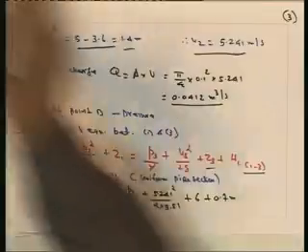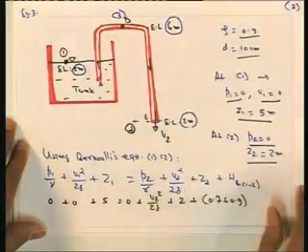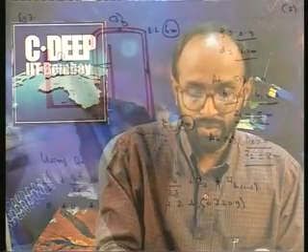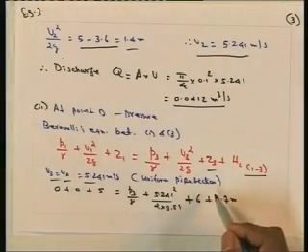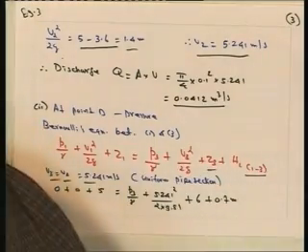Here you can see that this section is at elevation 6 meter from the datum. So, plus 6 plus the head loss between point 1 and 3, which is given as 0.7 meter. So, this is the Bernoulli's equation between section 1 and 3.